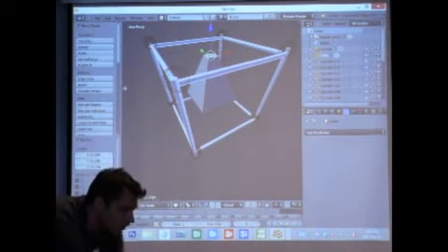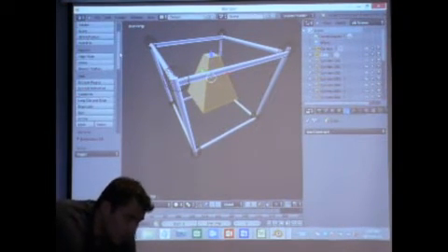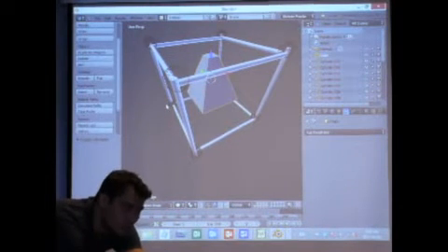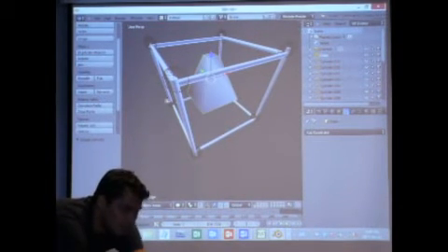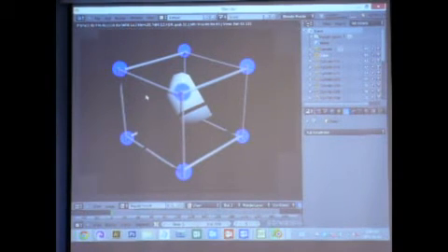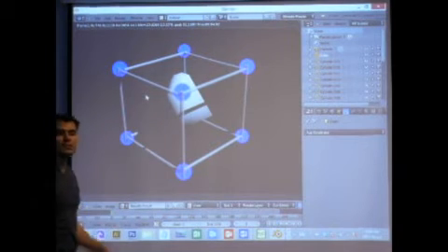Of course, if you select the whole thing, you'll notice on the left side, you're like, oh, I can't smooth the object, right? That's because you're in edit mode. If you press tab to move back to object mode, you can smooth it out to make it look much better. You have this cool looking pyramid structure. It's only partially lit because I have only a sun lamp, and you can add a light source to make sure it all works.